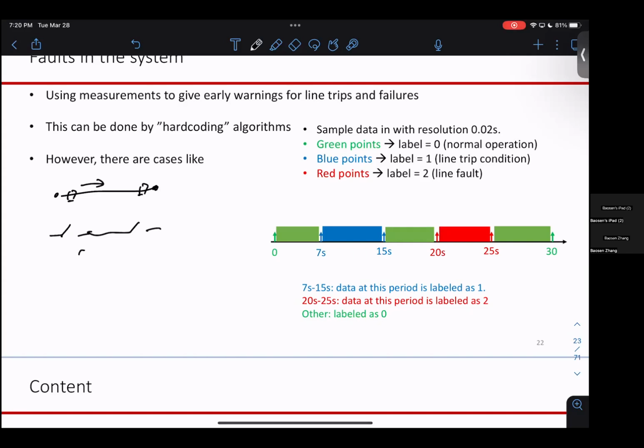Then what happens after, let's say some time, let's say 0.5 seconds, both sides will actually try to close. Because the breakers don't know whether there's a lightning strike, they just measure high current. So the default is you think it's a lightning strike, you open, you don't pass the current through, but then you reclose. Lightning has finished, your line is still there. Okay, so this is the protection device as you go green, blue, green.